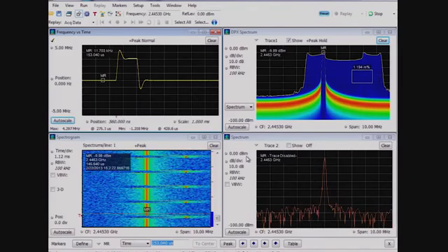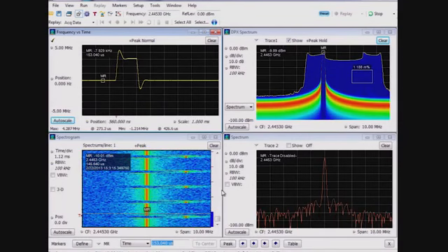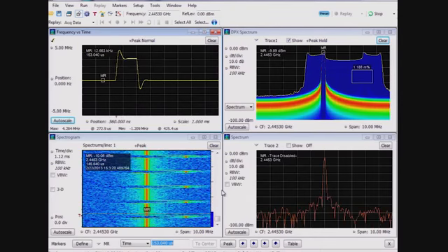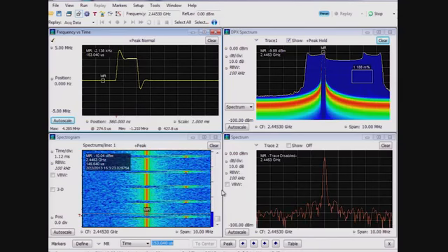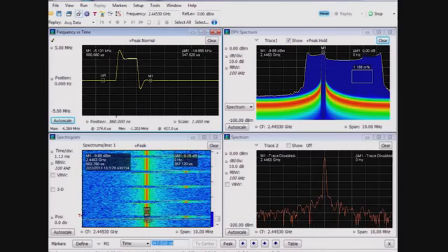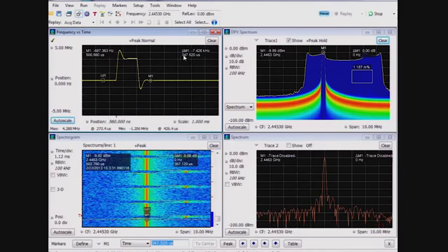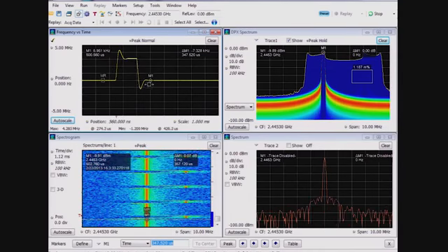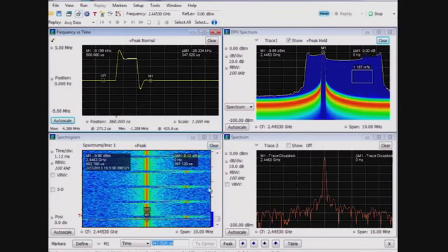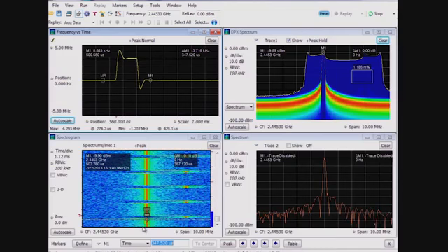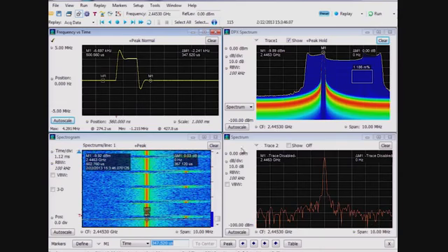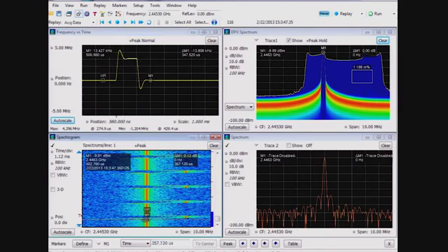One of the important aspects of the Tektronix real-time signal analyzer is that most all of the capabilities are integrated into the instrument software. Furthermore, if we put on markers to measure the transient that we have captured, we can perform a direct measurement on either or both the frequency versus time measurement or the spectrogram. The spectrogram shows the signal history over time, with the most recent signals appearing at the bottom and the oldest signals at the top. Last, the spectrum display's orange trace corresponds to a time slice of the spectrogram.